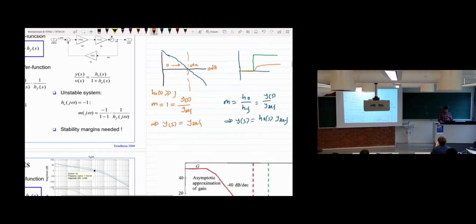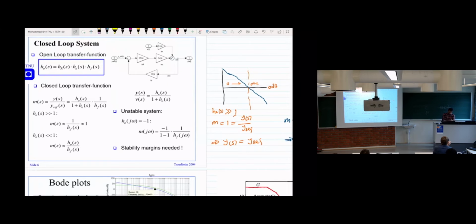So when we derive the closed loop transfer function, we consider that we neglect the disturbance part. Now we also want to see the impact of the disturbance. When we want to see the impact of the disturbance, we neglect the input part, this reference part. So if we neglect this reference part and derive the transfer function, you will find the transfer function like this. So this is the transfer function you get considering the disturbance.